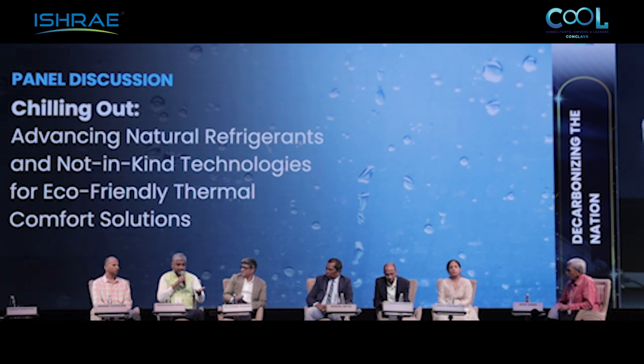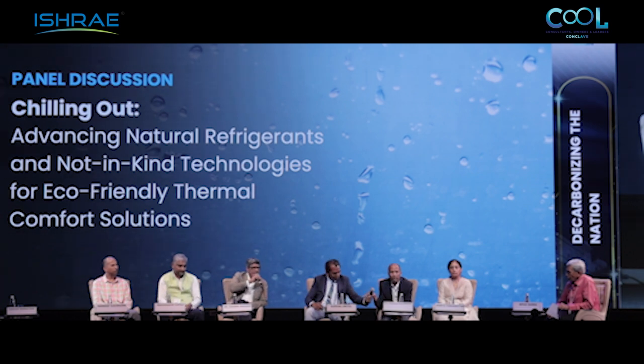They are already being used in many industrial environments, such as food and beverages, where there is a lot more muck in the ETP water, and you are able to use them as heat sinks. Traditional fin and tube with copper and aluminium may not work. But here is a good example of a polymer heat exchanger delivering excellent results. So we need to start looking at polymer heat exchangers if the water is more aggressive. Is there any other question?